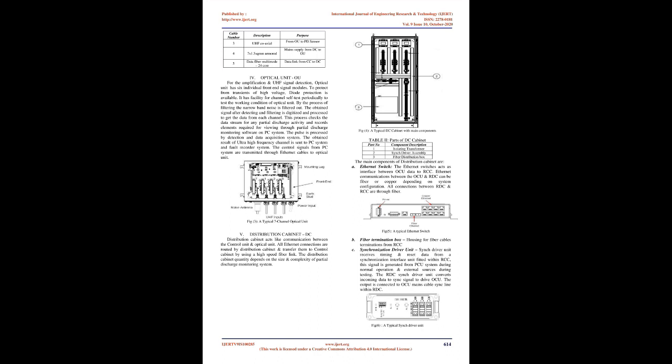3. PDMS partial discharge monitoring system. The PDMS system plays a crucial role for continuous monitoring of the occurrence of partial discharges in the gas-insulated switchgears and to communicate, updates the same in the HMI as well as the remote control center. It has 3 main panels known as OU optical unit, DC distribution cabinet, CC control cabinet. The general arrangement for PDMS system can be represented as below.